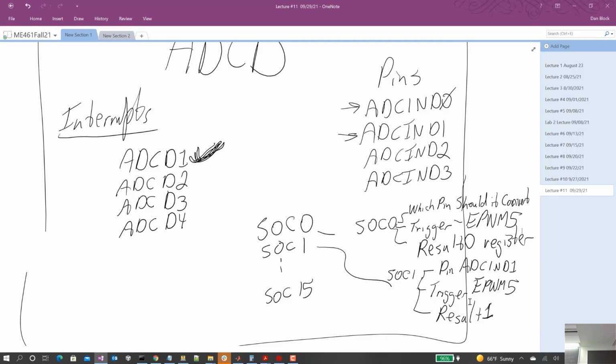You could technically have the interrupt be called when SOC 0 is done converting, but then when you get into that interrupt function, SOC 1 may not necessarily have been finished already. So obviously you want to wait till the sequence is finished. Let SOC 0 convert, then SOC 1 convert, and then generate the interrupt.